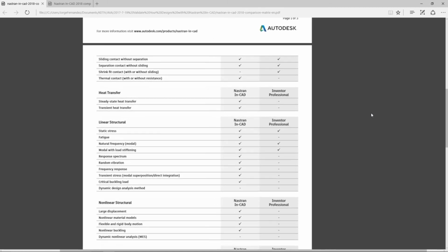All right. But generally, some general guidelines: fatigue, Nastran; heat, Nastran. Static stress, both. Dynamic, quote unquote, both. Yeah. One's a little bit easier than the other, like Jorge mentioned.